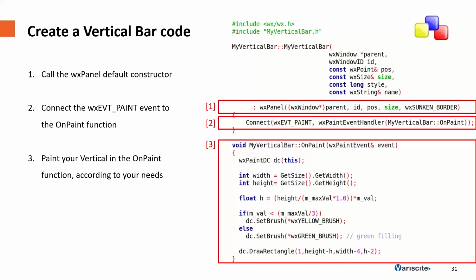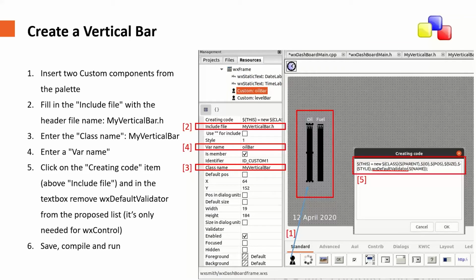Once we do this, we still have to introduce our new control in the graphical design. How can we do this? Basically, in the list of possible controls that we can add, one of these is this strange keyhole with the question mark. This refers to generic custom components. When you select this component, you can select which include file is to be used, and this is the one that we created in the last step.